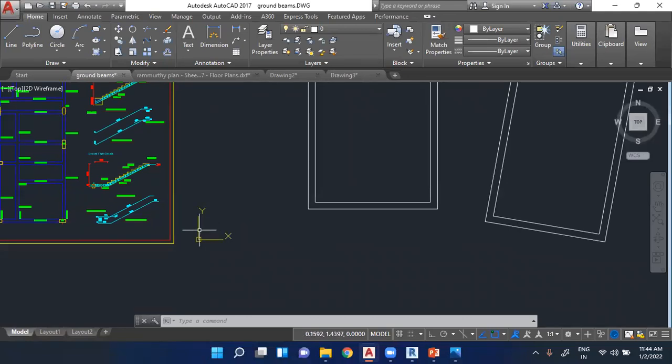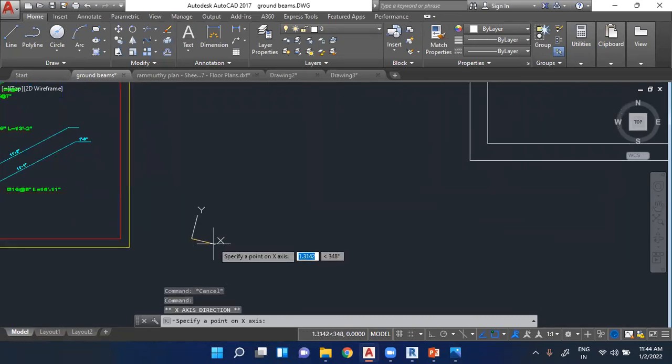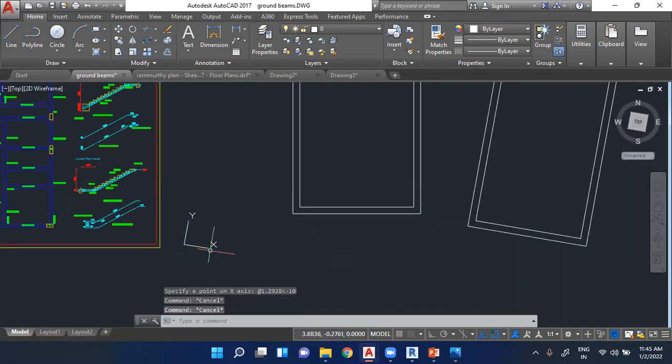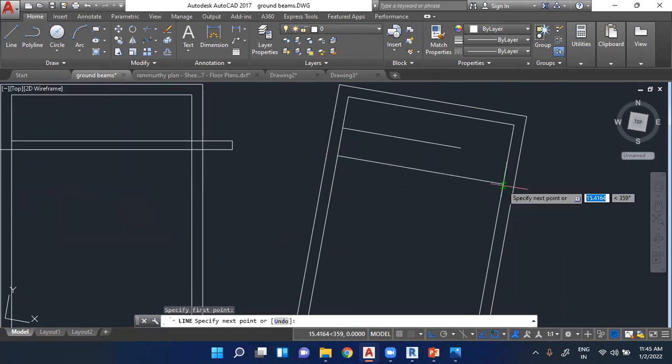So the best option to ease our work is to just change this coordinate system and tilt it by 10 degrees. Now when I'm working on the tilted building and want to put partition walls, by clicking this orthogonal mode on, after tilting that one, I can just put it as how I was working on the straight building.